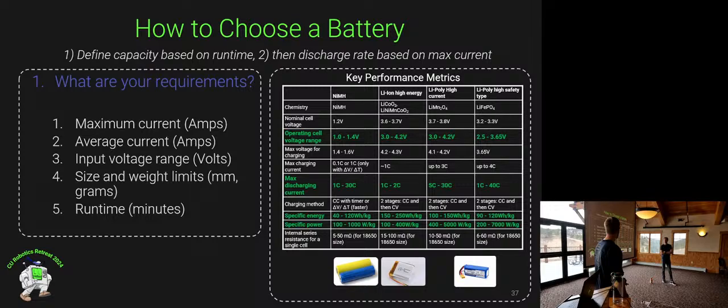I personally don't. I've basically just picked LiPo batteries for the most part. My understanding is that lead acid is bad. Lithium iron phosphate is safer. I think those are the high safety ones, and generally they don't burn as easily. So if you were doing a firefighting robot or something, a LiPo fire would probably be a really bad situation. But maybe for a system that's going to be in higher temperatures, that might be the option to pick.